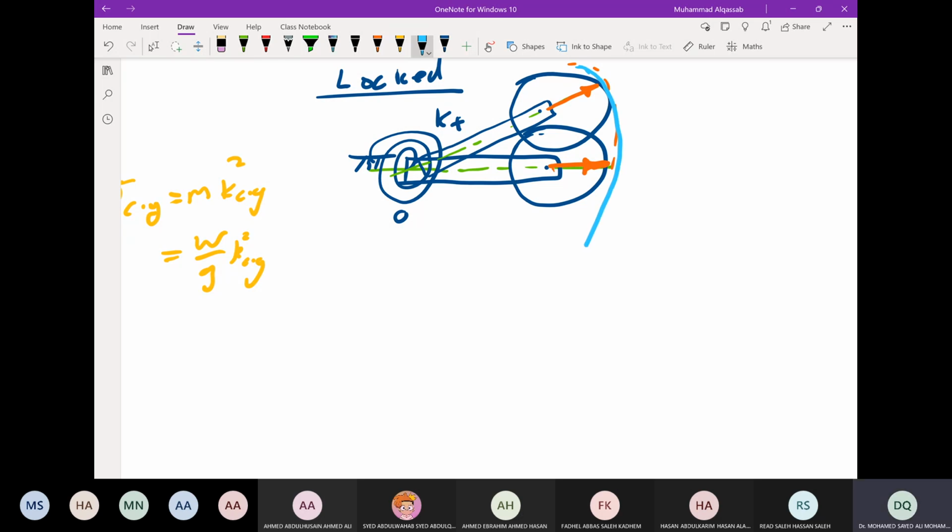Okay, there should be a contact point. So the type of motion of the wheel is general plane motion, translation and rotation. That means if you place a line on the wheel, you will see that line is rotating with the arm with the same amount of displacement theta. So the type of motion is translation and rotation for the wheel.